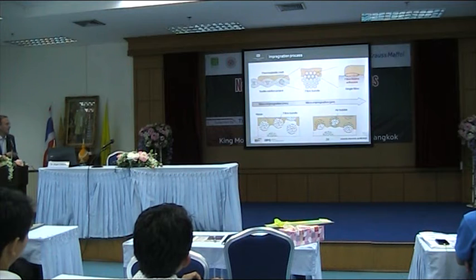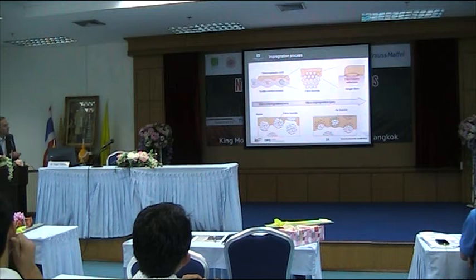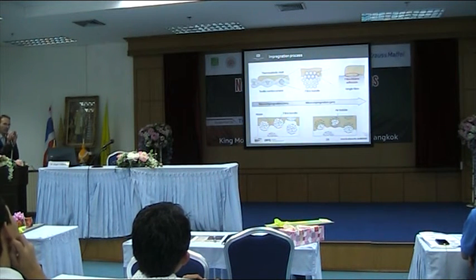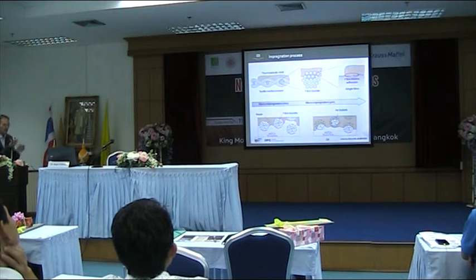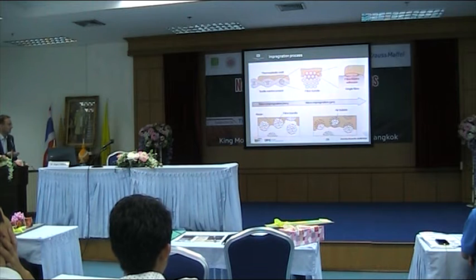So the fiber bundle, and this we also know from natural fibers, has a lot of single fibers, and they are then produced into textile prepreg. And we have some flow gaps. Here you can go into the textile, but especially difficult is to go into flow gaps between the single fibers, because they are often really compressed so that you do not have so many flow gaps between them. And that is the problem to get thermoplastic prepregs.